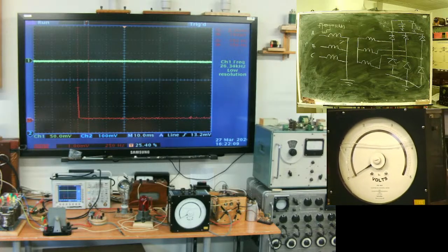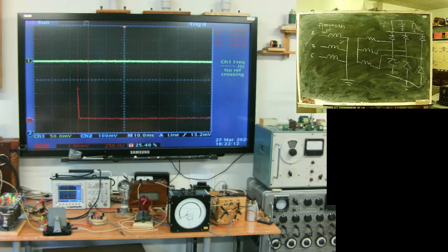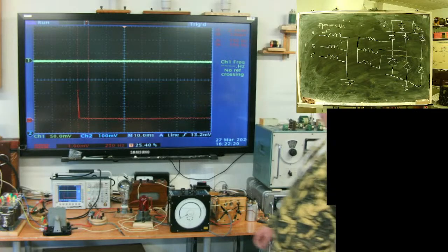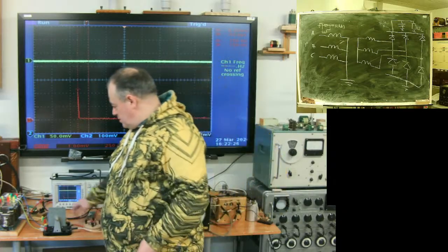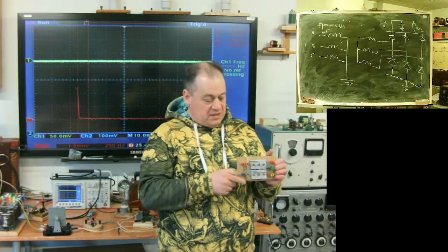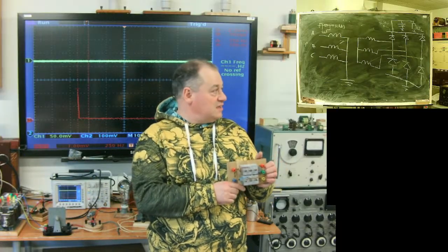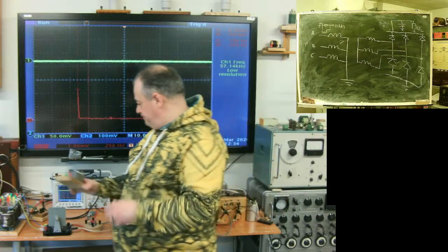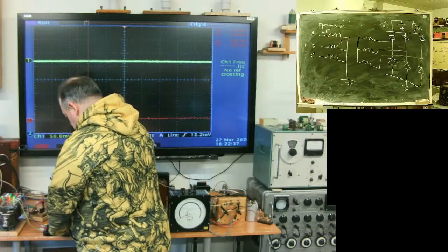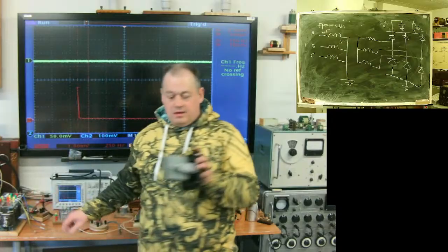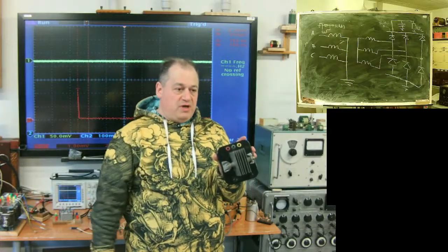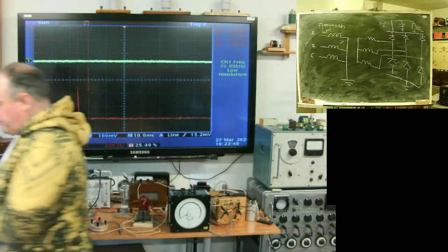In that rectifier we have 4 diodes inside. Here 6, 6, 6. It's full bridge. For single phase, 4 diodes, typical. In case of full bridge for polyphase, 1, 2, 3, 4, 5, 6. Yeah, 6. Here, 1, 2, 3, 4, 5, 6 plates. Polyphase full bridge.